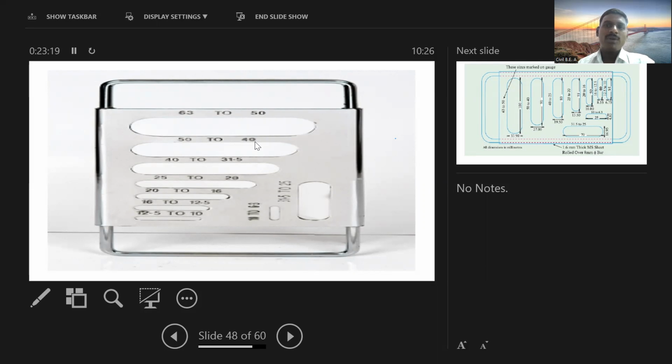It is very, very important to decide the size of aggregate, because of these sizes we have elongation and flakiness to keep in mind. Depending on the size, the mixing of that particular layer is very important.